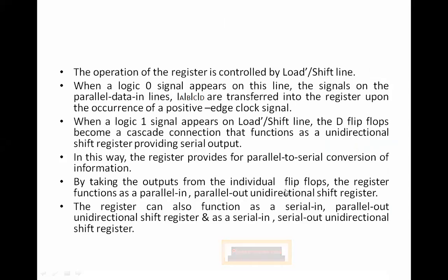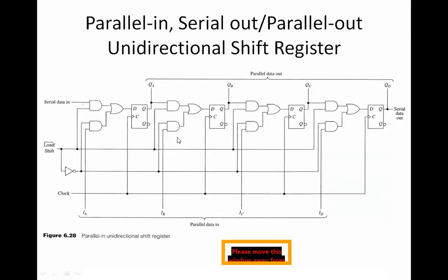By taking the outputs from individual flip-flops, it functions as parallel in, parallel out, unidirectional shift register. The register can also function as serial in, parallel out, unidirectional shift register, and as a serial in, serial out, unidirectional shift register. So as I mentioned, this circuit is very special. It can act as multiple things. Serial in, serial out, parallel in, parallel out, many things.